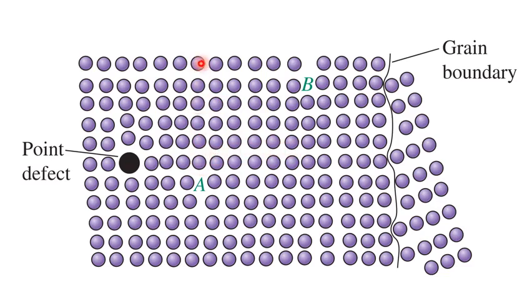Now dislocation A moves in this direction freely until it reaches dislocation B. Because the structure of the material at dislocation B is not the perfect structure, dislocation A needs higher stress to pass through the area here.